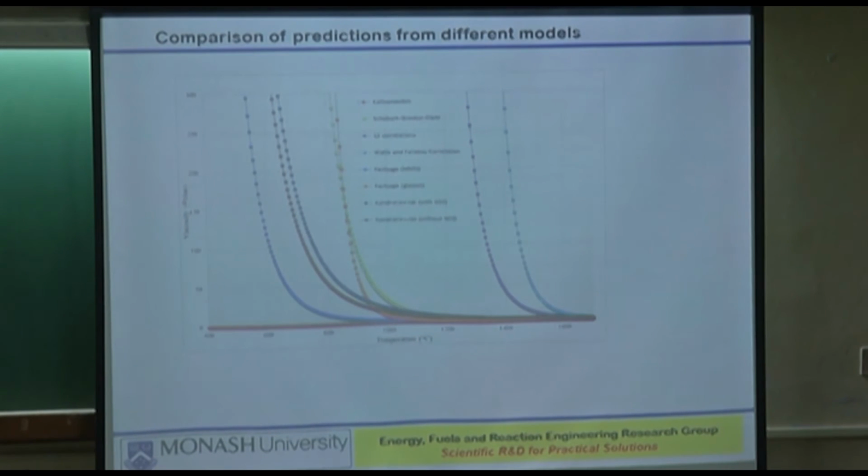After the experiments are done, everything has to be cooled down, the crucible has to be retrieved very carefully, and inside all you can see is something like cement, and a distinct boundary of the solidified slag. So you take it out, subject it to XRF, EDX, X-ray diffraction and all the associated preparations, then put it in FactSage again, put it to a phase diagram, and get all the compounds, the elemental and the compound information. Everything is crystalline, that is the beauty of it though.